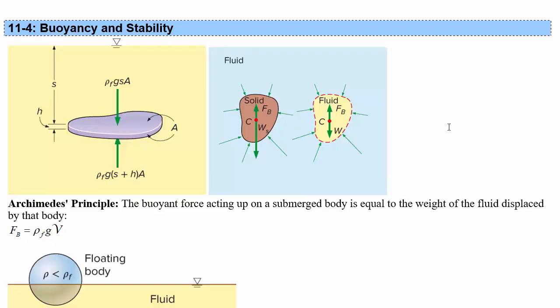The very last section for today, buoyancy and stability, is going to be for objects that are completely immersed in the fluid. And now we can do a trick where we don't have to do the calculations of the last section. So the force for something that's completely submerged, it's surrounded by fluid on all sides, it's not like a wall or anything, is going to be balancing out in all of the horizontal directions regardless of the shape, and we're only going to have a net vertical force, which we call the buoyant force.